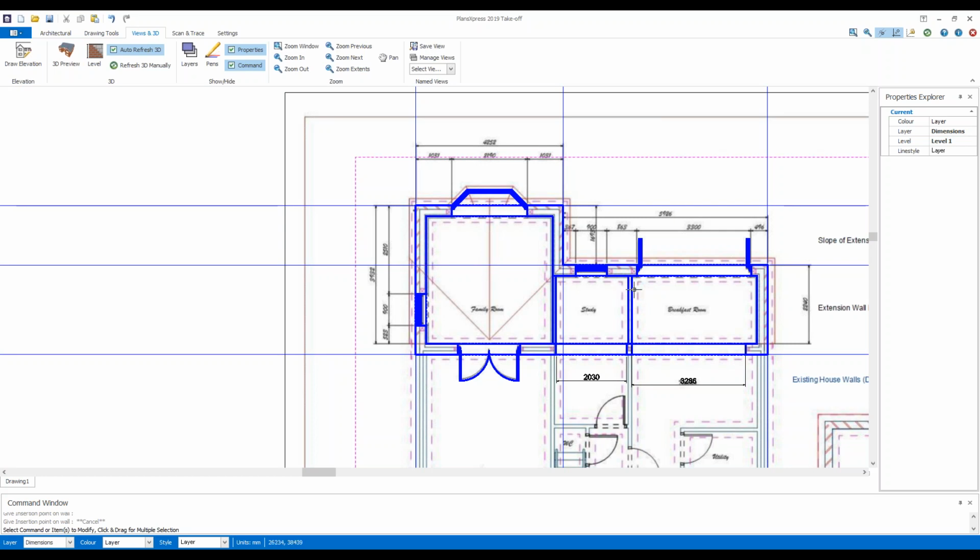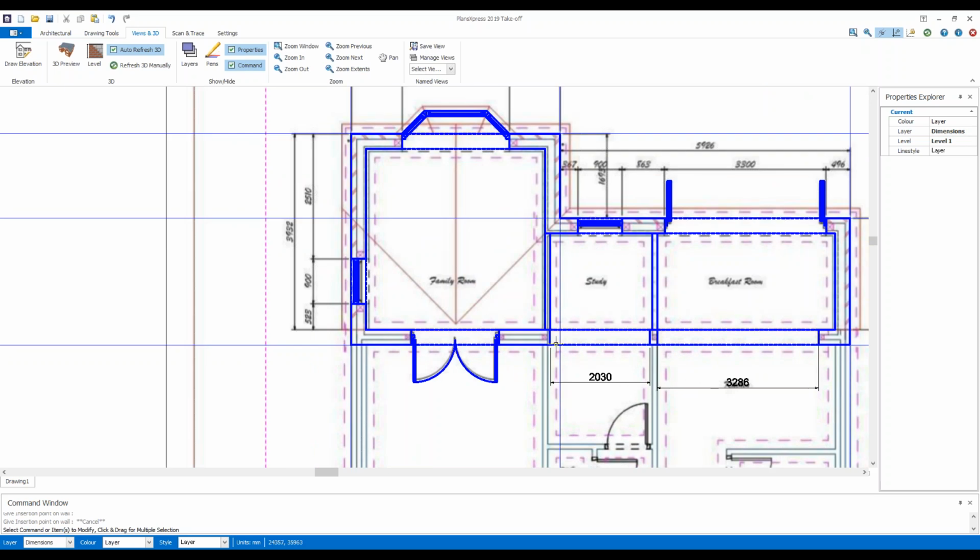I'm assuming you're all still with me. You might be wondering why I didn't put a floor in first of all. The reason I don't put a floor in before I start drawing things like openings is because of these. I'm not sure if you can see what I'm circling around, but I'm circling around the structural openings and the door openings. You need to calculate a slab or suspended timber floor for the ground for all of this area, not just for the central bit. So I like to do freehand all the way around the perimeter. And that way I know I've got enough materials later on.